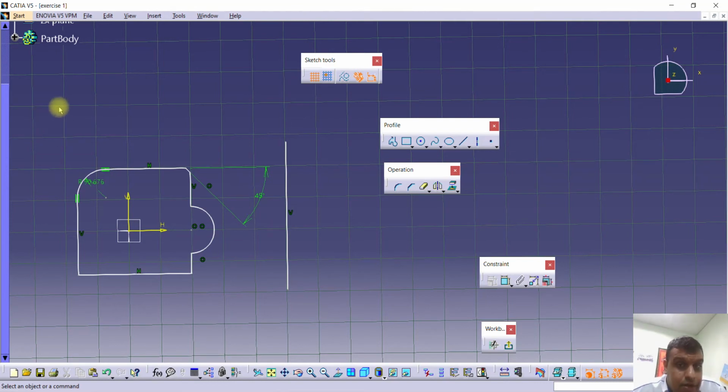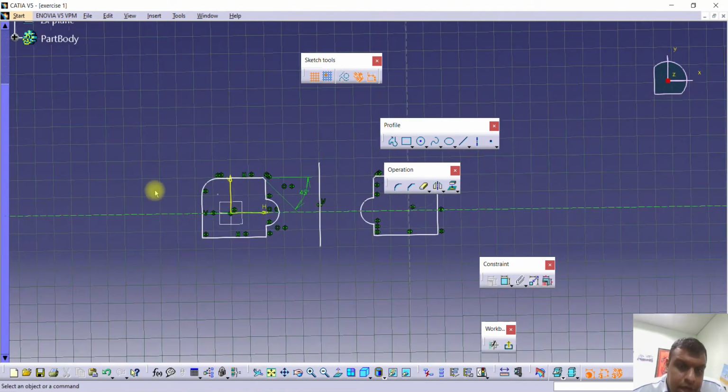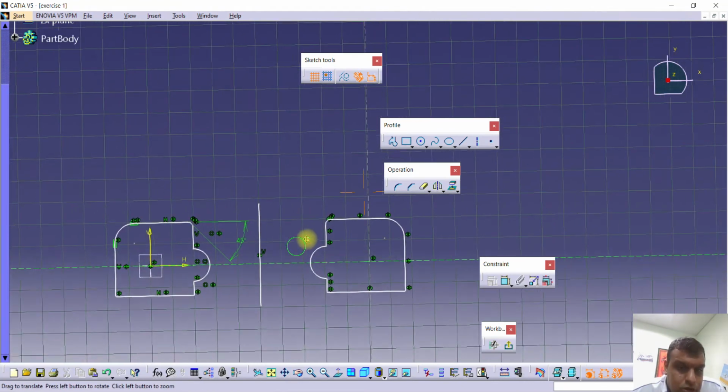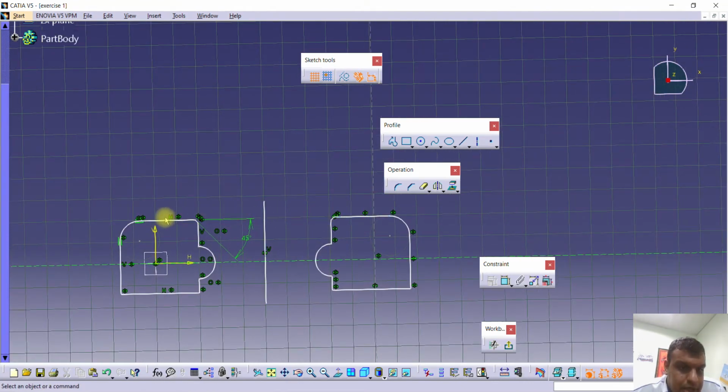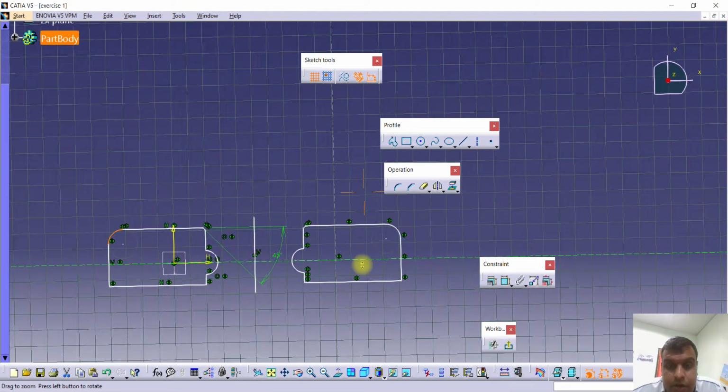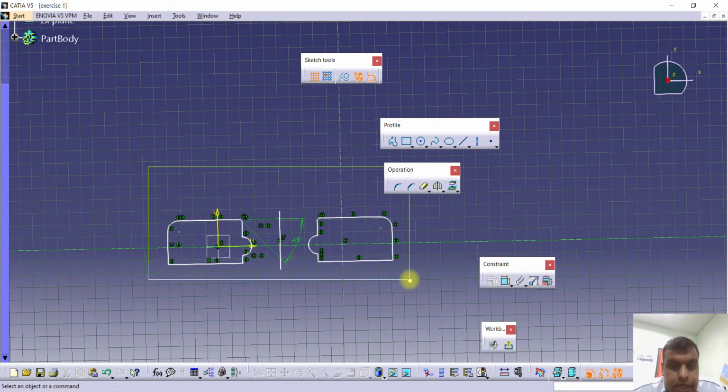Now you first select what you want to mirror. Select the part you want to mirror, select all, and then you click mirror. After that, you can click exit. Select exit. The part is now mirrored. If you change this side, this side will also follow. For example, I just drag this line, and this line also changes because this part is the mirror part. It's a basic thing.